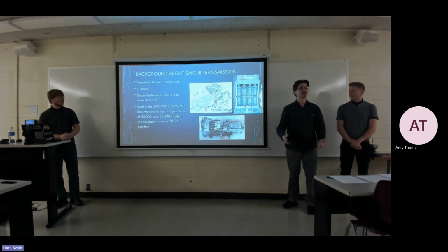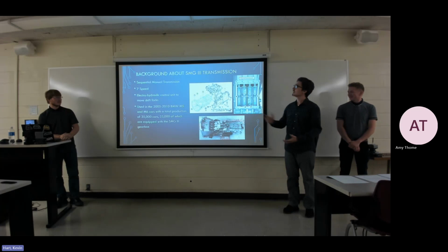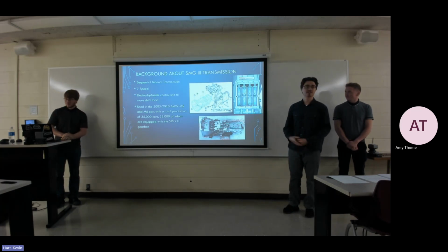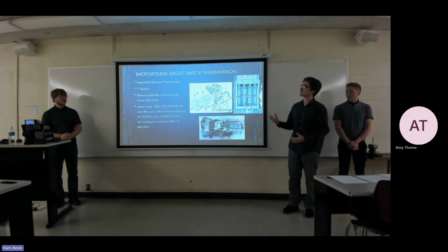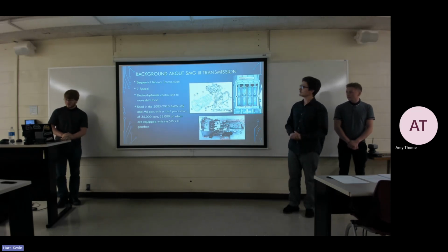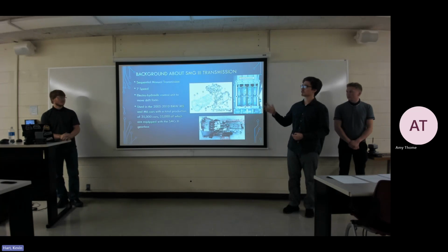So let's start with some background research about the SMG3. It is a sequential manual transmission. It is 7-speed, and it is a single clutch automated manual transmission. And this transmission is found in about 33,000 BMW models. And this unit uses an electro-hydraulic control unit to move the shift forks.